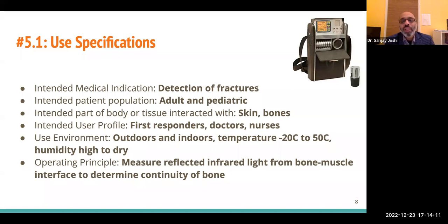Now, all this means is when you write it, you can immediately see how this is going to reflect in your design requirements. For example, when you talk about temperature range, you are going to select the electronic components that can withstand this range. Same is true about humidity, and we are going to dig a little deeper on how this drives your requirements.